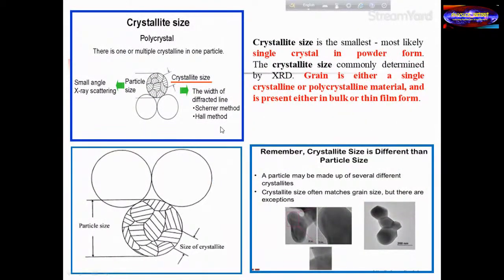Then for structural analysis, we need powder XRD diffraction, and also single crystal X-ray diffraction to identify single crystals. Here, with powder XRD, we are measuring the crystallite size. This is not the grain size, not the particle size. A particle consists of lots of small crystallites. So these are all crystallites, and the interatomic distances we calculate from the spacing in the XRD. The particle or grain consists of small crystallites, and X-ray can see only the crystallites and interatomic distances. So XRD gives you the crystallite size using the Scherrer formula. We can never measure the particle size or the grain size with it.